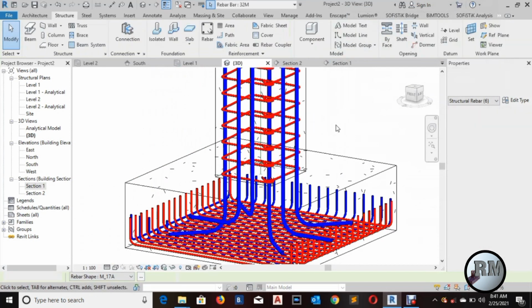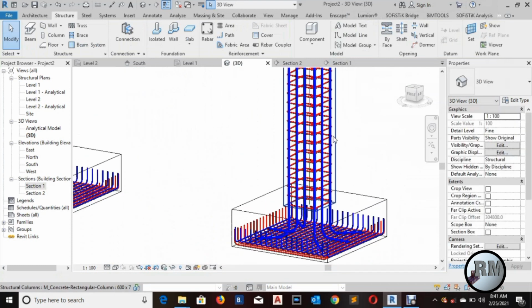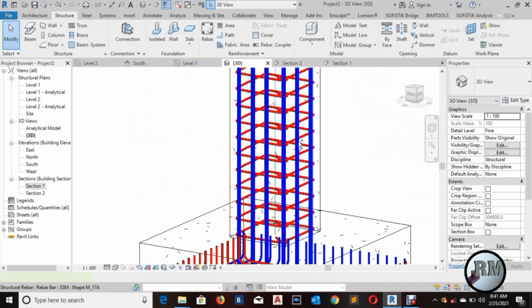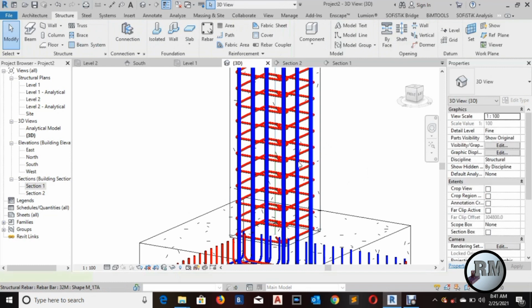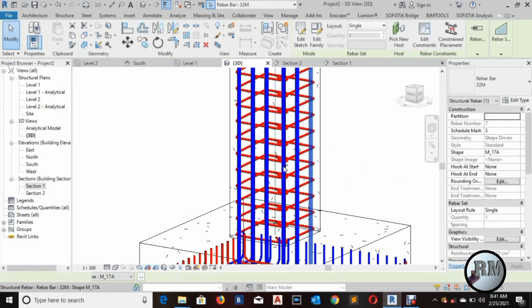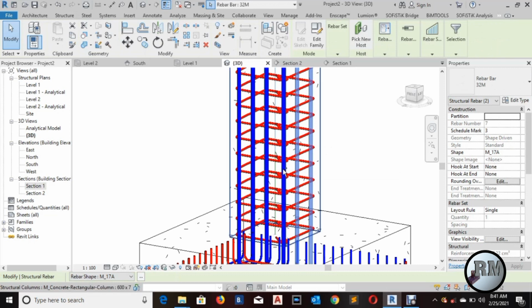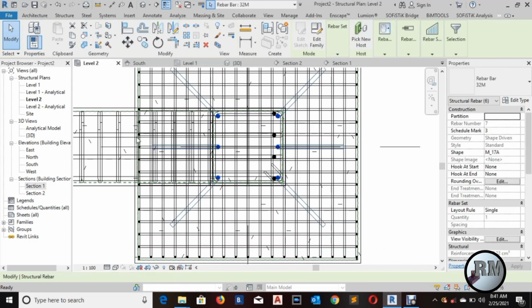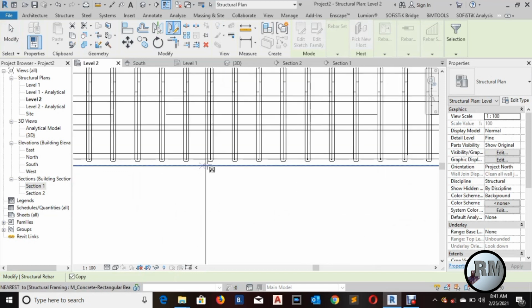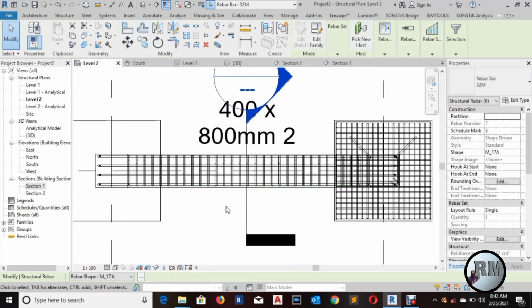So this is what we have. So we can just select these bars, control select, just select them like this, then go to level 2, then select axis and go to the middle of this beam until you find this triangle of midpoint, and select and drag it down so those rebars may be copied to another beam.